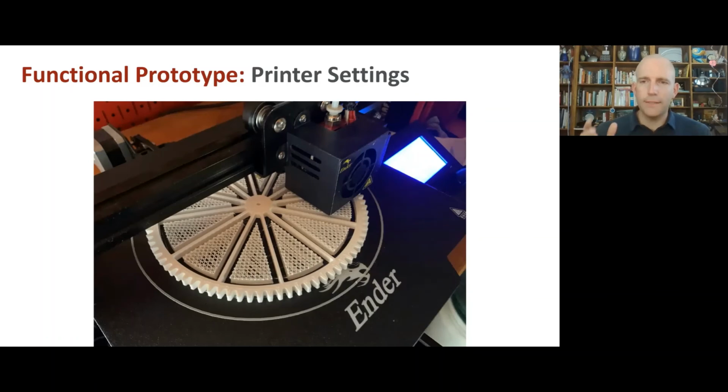So we have a pretty stiff surface to hold those teeth so they don't bend too much, which can cause them to grind or have higher friction. And here's a support surface. We've got these fins so this thing has stiffness in this sort of outer plane movement. And then there's a central sheath that provides the torsional stiffness.